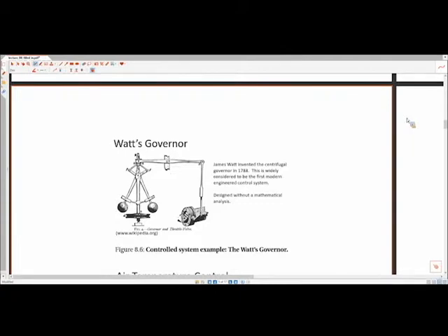So more air burns hotter, more steam, right? Less air doesn't burn as much, less steam. So you can control the flow rate of air by this valve here. And so the way in which this valve is controlled is via mechanical linkages. These mechanical linkages connect to the flywheel of the steam engine. So it's actually spinning, which determines how fast your steam engine is going, is mechanically connected to this flywheel, and this flywheel rotates on this axis.